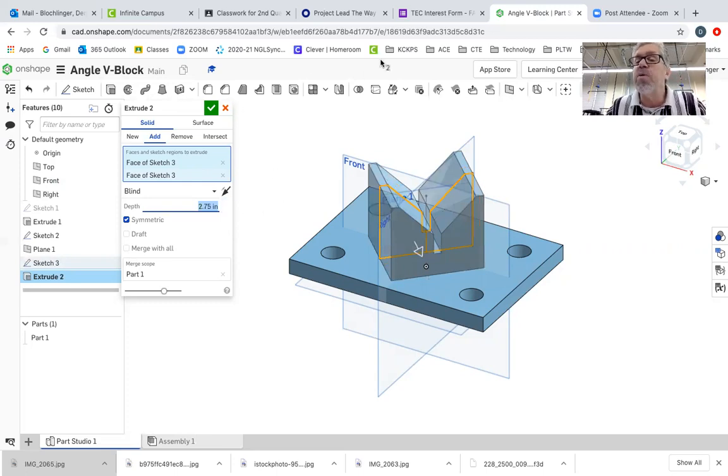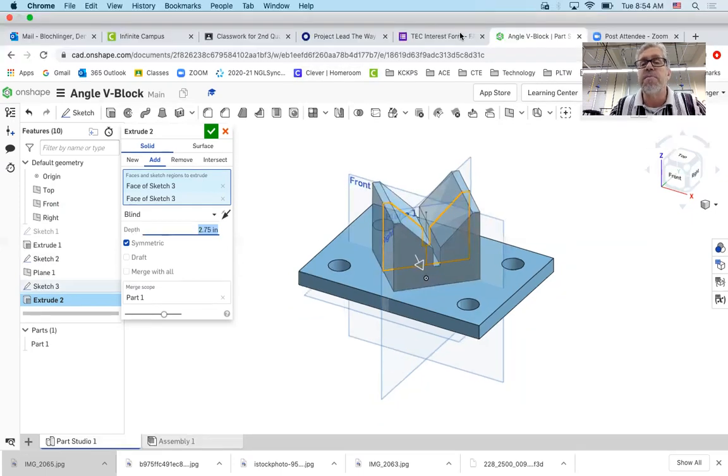All right, I'm going to leave it with you from there. You've got to put it in the title block and dimension it, right? What else? Yeah, when you put it in the title block, I need to see all visible lines, all hidden lines, all center lines. Then we add our dimensions on the 3 views, starting with the circles first and the angles on the view that shows them, right? And then we go to the smallest dimensions next on the view that shows the true shape. And then we add the overall dimensions to help us balance the three views with dimensions. Okay, hey, good luck with it. I'm going to leave you there.